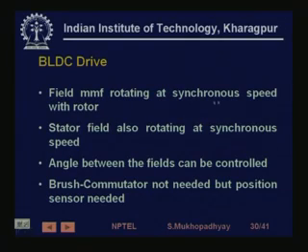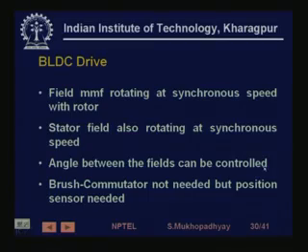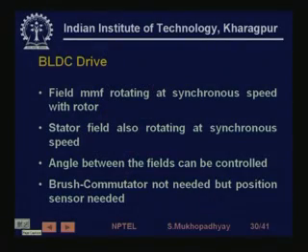Your rotor field is rotating at synchronous speed and the stator field is also rotating at synchronous speed, and this is achieved by switching, and the angle between the fields can be controlled. Therefore, you do not need any brush and commutator, but you need to see when you will switch which stator phase, and that depends on the rotor position, because you want to keep 90 degrees. So, you need to sense rotor position. The principle is very simple.